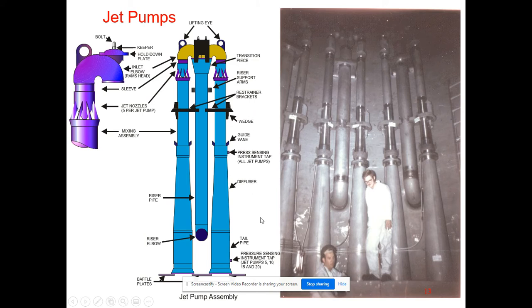So here you can see the jet pumps. We've seen this picture before. So the recirc pump comes in these two. It splits into the two flows here, and it's going to go up. Oh, I apologize. I'm saying it backwards. It's going to come in the middle here and split off into two. And then there's a nozzle right here. And at the end of that nozzle, you're getting that Venturi effect. So the pressure gets very, very low right at the tip of the nozzle.